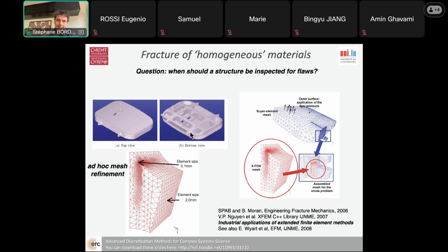And the reason why everything happens here is quite logical, because all the boundary conditions are effectively applied through the center of that stop, which you see maybe better here on the right-hand side. So the center here is where you bolt that thing to the fuselage. So this is what prevents it from leaving, really, the aircraft and starting to fly away.